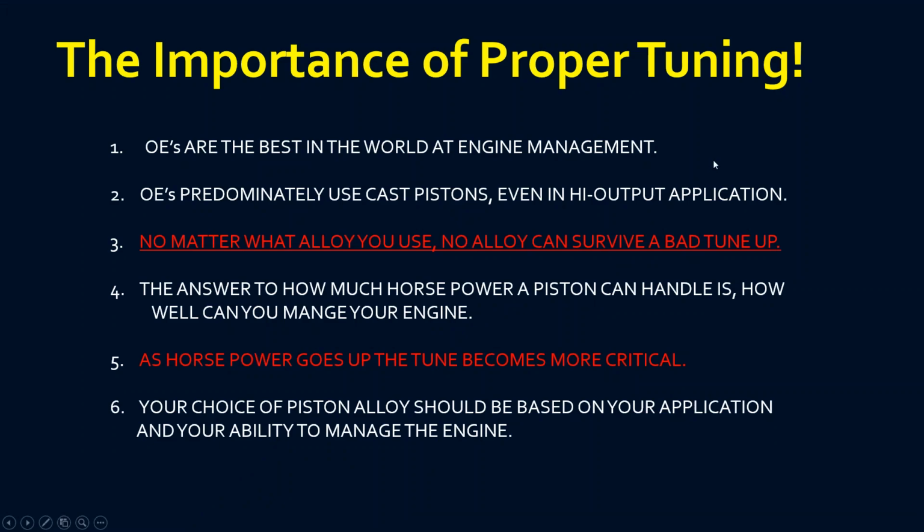Now, here's sort of a disclaimer, and it's about the importance of proper tuning. If you look at the OEs, they're like the world's best at it because that's all they do, and that's all they're focused on. Their one particular engine could be high output, but they'll just use cast pistons in it. And they do it because of the tuning, that they make sure that the air fuel mixture, the timing, everything is there that can not destroy the cast piston.